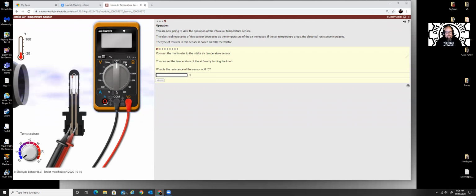We're not going to be measuring in the millions of ohms, I don't think. Okay, 200 ohms? Possibly 2,000 or 20,000. Depending on the kind of sensor you have, you may end up dealing with thousands of ohms, all right? It's always a safer bet to start low, okay? Oh, there we go. You see this movement I'm making here? My mouse has a thumb wheel, a finger wheel on it. As you use your finger wheel, that's going to adjust that. If not, the clicker is going to work. So let's start at 200 ohms.